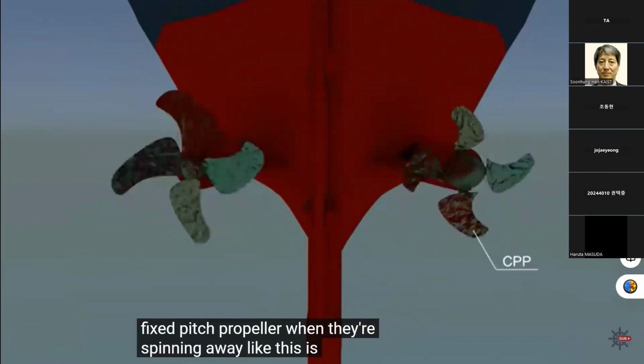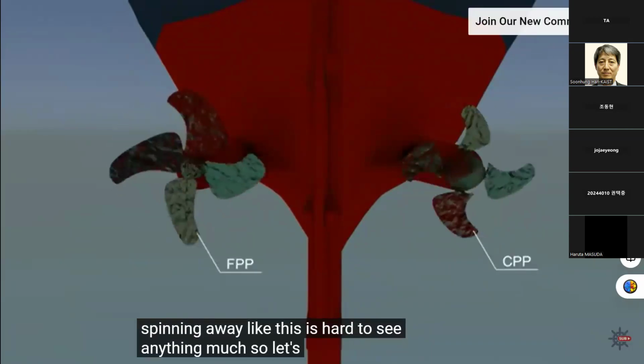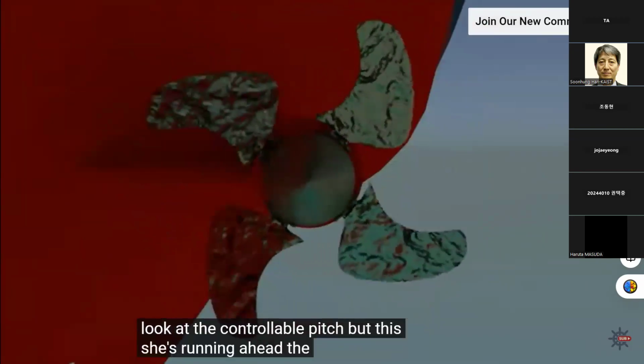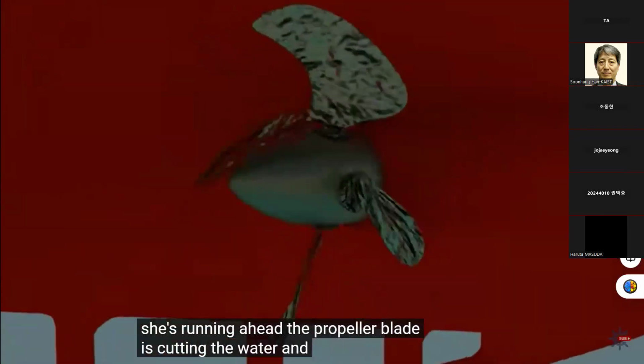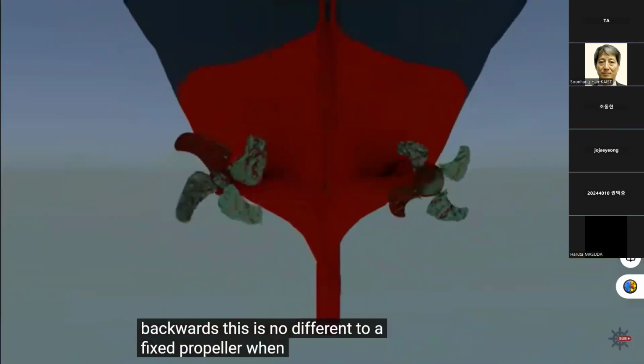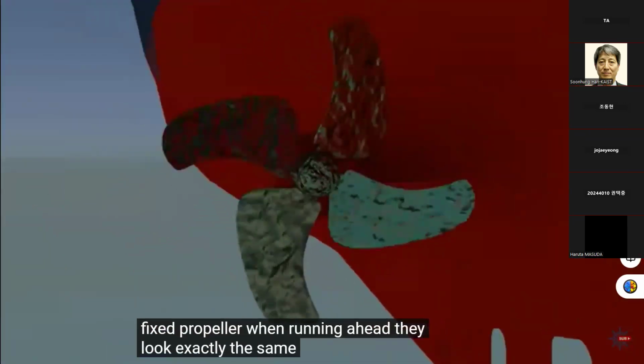When they're spinning away like this, it's hard to see anything much, so let's slow it down and look at the controllable pitch. Like this, she's running ahead. The propeller blade is cutting the water and propelling it backwards. This is no different to a fixed propeller. When running ahead, they look exactly the same.